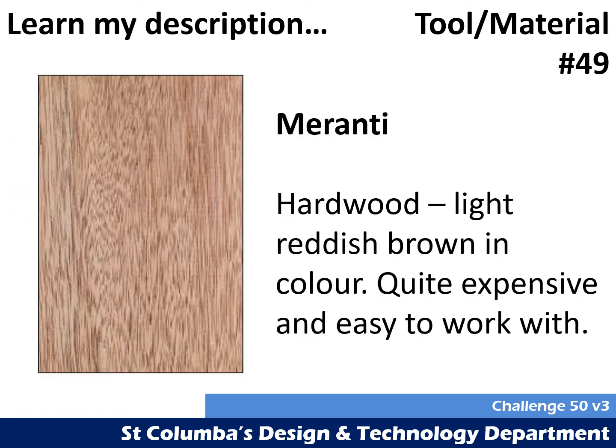Material number 49 is Meranti. Meranti is a hardwood which is light reddish brown in colour. It's quite expensive and is easy to work with. Meranti is sometimes known as Philippine mahogany. It has very similar appearance and properties to mahogany, but it's slightly less expensive than mahogany. It's slightly more available, slightly less rare than mahogany. Commonly, the mahogany substitute that we would use in a school workshop is Meranti.